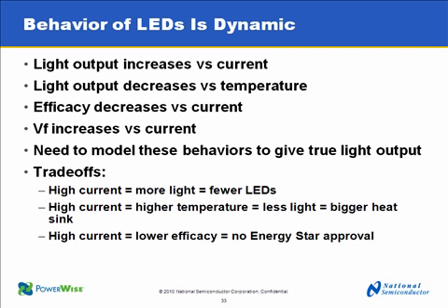And why did we do this? Well, what we just saw in the prior example was the LED behavior. We had a typical light output in lumens, and let's say it was at 140 lumens. The thing is that light output is only for 25 degrees C, and we don't necessarily always operate at 25 degrees C. Also, if we can increase our current, we can increase the light output and get perhaps more light out of the LED than the nominal. So if an LED is rated at 0.35 amps, maybe we can drive it at half an amp, get more light out of it, and use fewer LEDs.